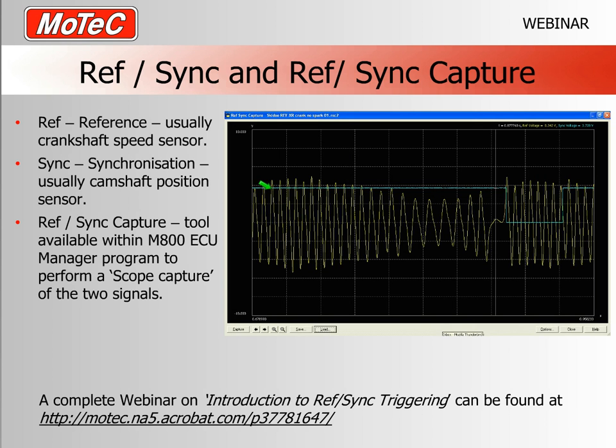So what you can see are two different voltage levels, and this capture shows the engine rotating quickly as these waves here move further apart. It's because the engine's actually slowing down when it hits compression. And then what we're seeing here is a missing tooth event, and this is one of the ways we use a reference sensor to tell us whereabouts in the rotation it is.